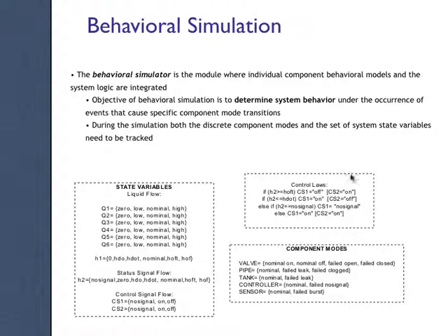On the top right, this box here, the control laws, this essentially takes the information in the state variables and how the system is supposed to work and develops some laws or equations to make sure that the control is working correctly. So obviously in a situation where we didn't have any sort of control, like in the flashlight for the previous homework assignment, these control laws wouldn't exist. But essentially what they say is turn a control signal on. There's control signal 1 and 2, which are associated with valves 1 and 2. So turn a control signal on given that a particular value is met.